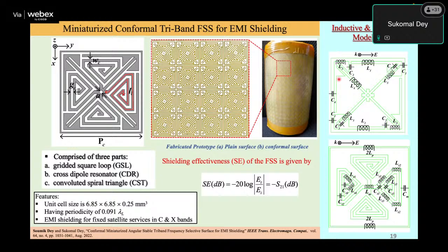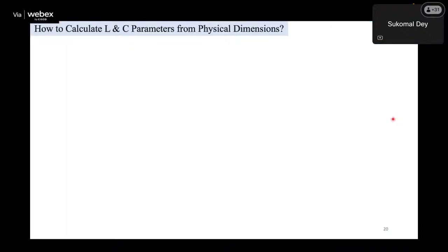Okay, and now this is for the outer ring. You have two rings, right? If you closely look at the structure with respect to my green color, you have two models. One model is this. Inside you have one more model. Now why are these inside models placed? To make the structure more compact and to get more inductance and more capacitance out of this structure. Okay, so it is placed over here and it has become the final structure like this.